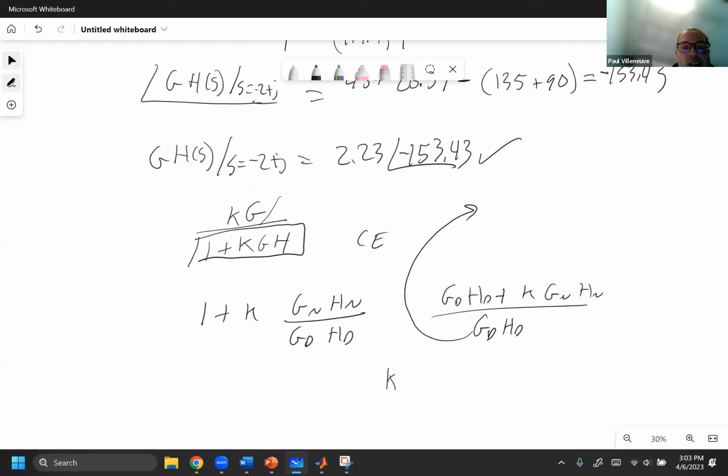And if we recall, our K is going to be greater than 0, but less than infinity. I always have to go back to when I was in grade school: the alligator mouth always opens to the bigger of the ones. So if K is 0 or very close to 0, these are the only two terms that I have. Those are the denominator terms for both the G and the H. These are the original poles of the system.